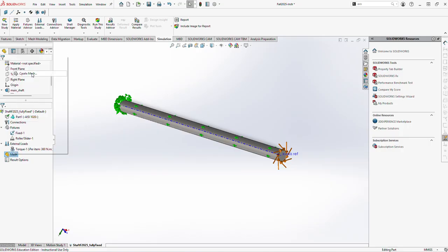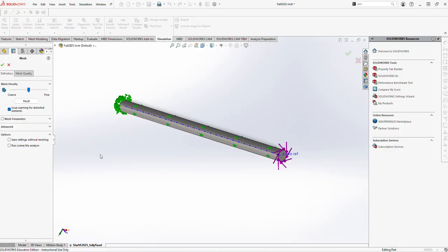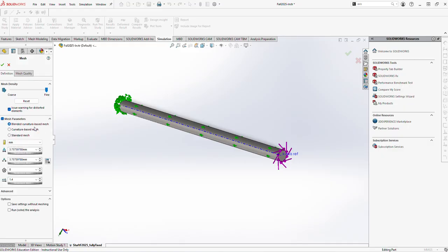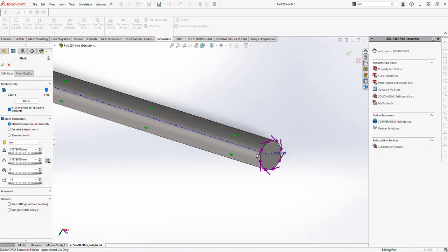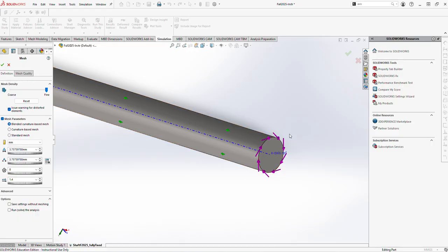In this case, we will create a refined mesh based on the blended curvature-based mesh technique. You can also use the standard mesh technique. It's not going to create a major difference. But I think in my case, I'll prefer using the blended curvature-based mesh simply because it's a circular part, and so it will all be meshed with the same sort of mesh.